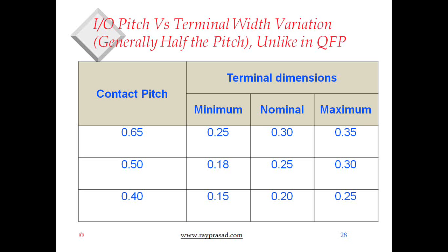You can have, especially in the gull-wing type package, really high defect. But in BTC, not so bad. But anytime the pitch goes down, you have a problem. So if I have an option, I want to draw the line at 0.5. Obviously, when you have to use it, you have to use lower pitch.